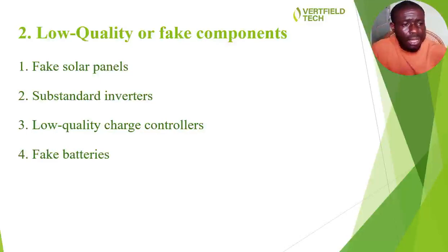Charge controller is another issue. Low quality charge controllers. When you are trying to build a super solar system, your charge controller can actually fail you, where you expected to use an MPPT charge controller and you end up using a PWM charge controller. A PWM charge controller is good to an extent, but it is not efficient enough. That is the truth.